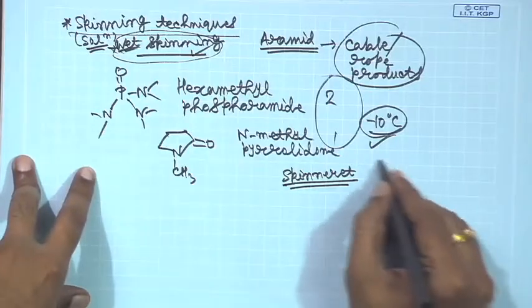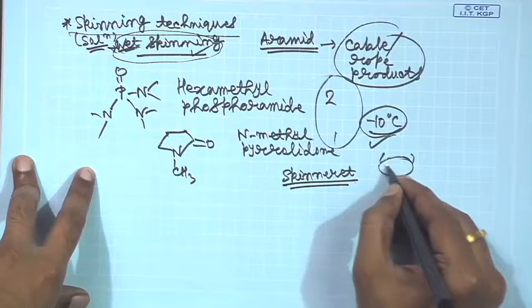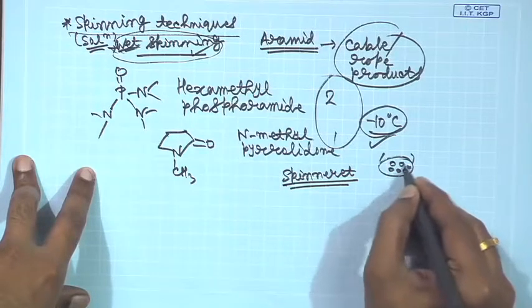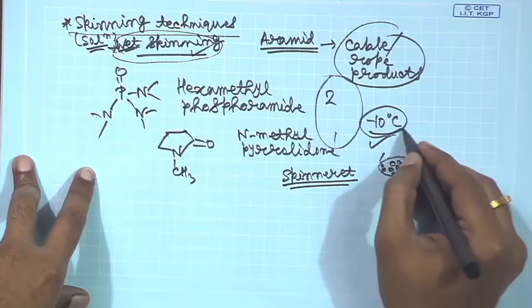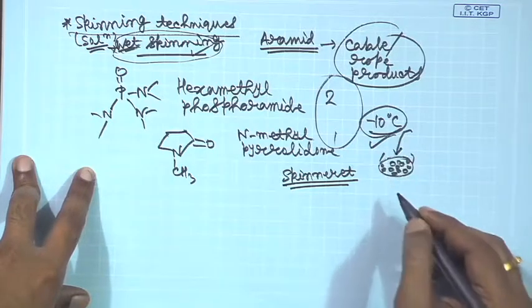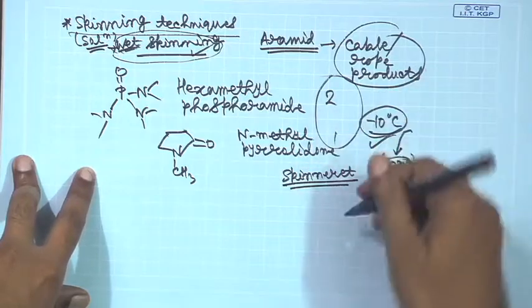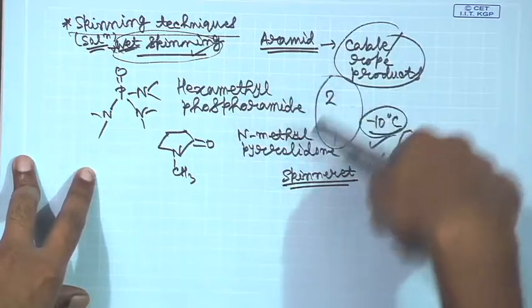I will come to what solvent you are going to use for para-aramids, but let us look at the properties that you would like to have in this precursor solution. So, you start with this solution and the idea is you will force it through something which is called a spinneret. These spinnerets, if you look at the script here, look like shower heads. These shower heads will have a lot of holes in them. So, what you do is push your polymer solution through this, you put a lot of pressure and you push it through, and that way you are actually orienting the material, the first thing.